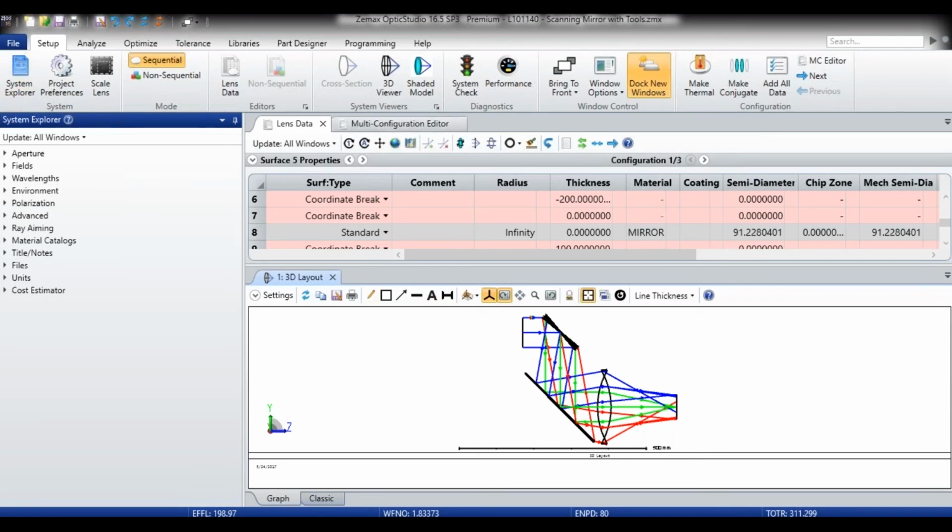There's a great webinar in our archives about stray light analysis, in which the presenter, I think, uses the double Gauss file, converts it to non-sequential, and uses that to analyze the stray light in the system. So that's always an option. But currently for illumination-based information, you want to use non-sequential. That's exactly what non-sequential is for.